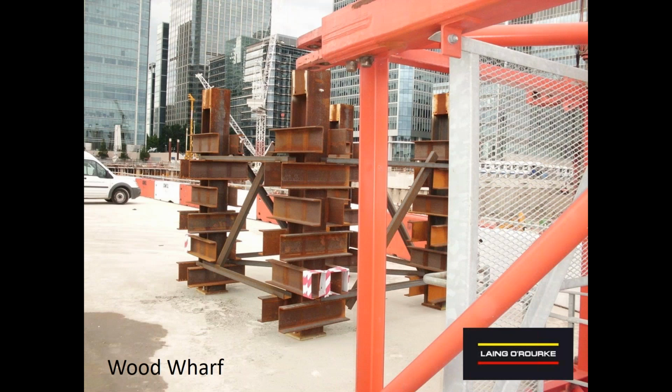In terms of the bases for high-rise cranes, this is potentially a base used for a high-rise crane, but it's also a typical anchor detail that might be cast in from a base for a low-rise job requiring, say, a 50-meter high crane with no ties. So the point really is that the base for a high-rise crane could easily be fairly similar to the base for a low-rise tied crane. If the crane goes from 50 meters to, say, 200 meters, then yes, you'll need a series of ties, maybe every 20 or 30 meters in terms of vertical intervals between ties.